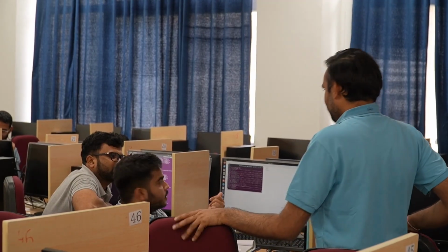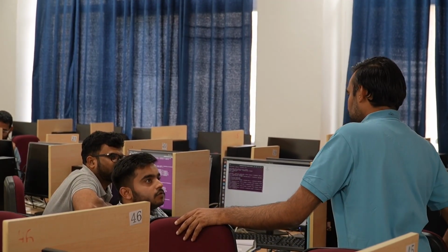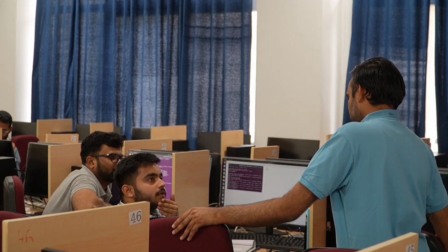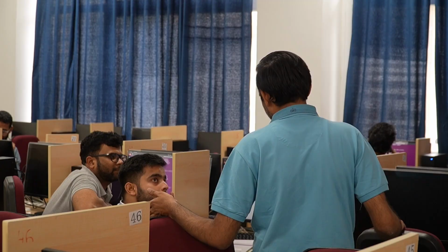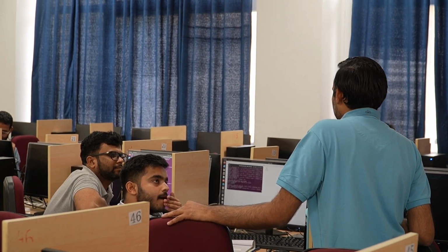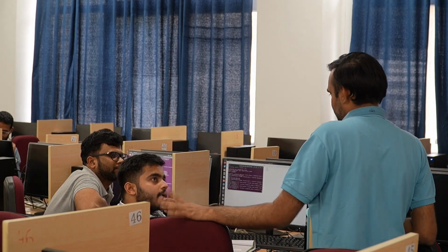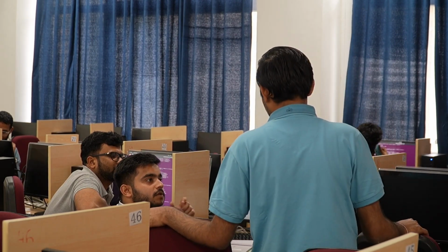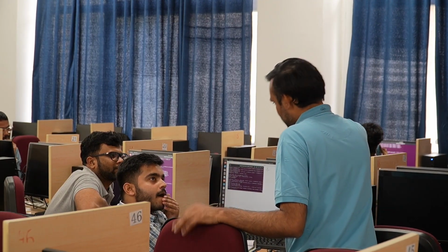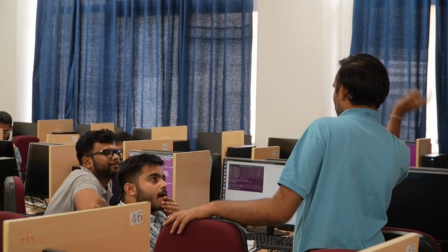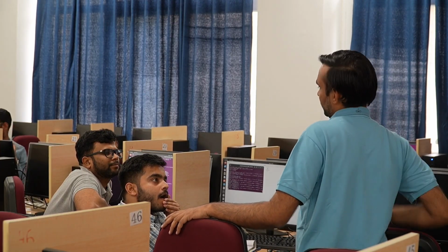And right now we are running the simulation. So what variables will it be saving at the back? UVW, all three components of velocity, alpha, the volume fraction, and pressure. So can we remove some parameters which are not required, like pressure? Yes. Typically this is the default writing format. If you have to remove that, you have to go to the source code, and there you have to select the appropriate variables.